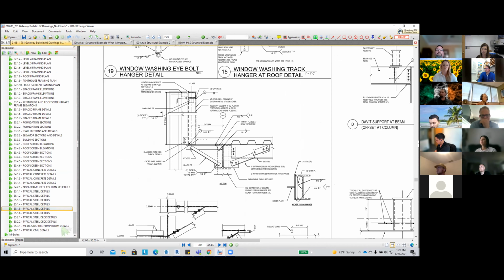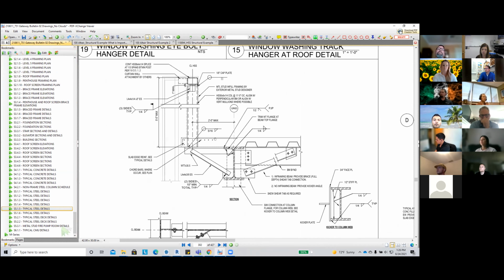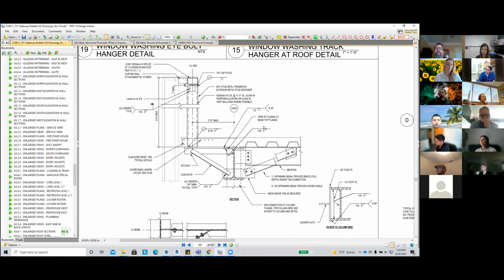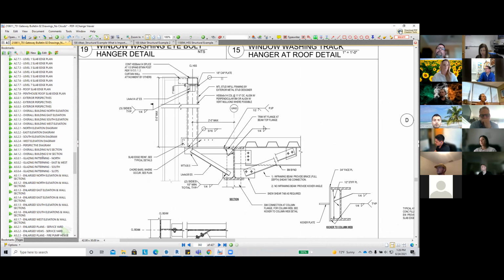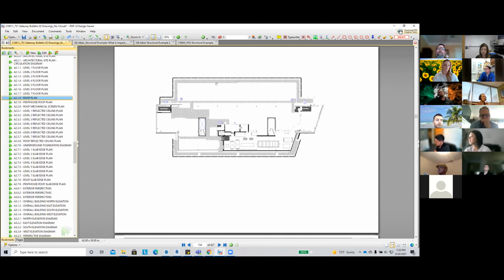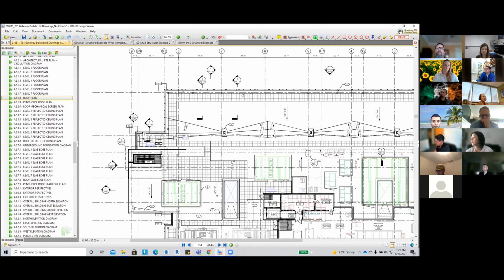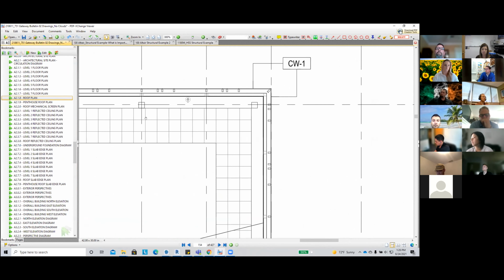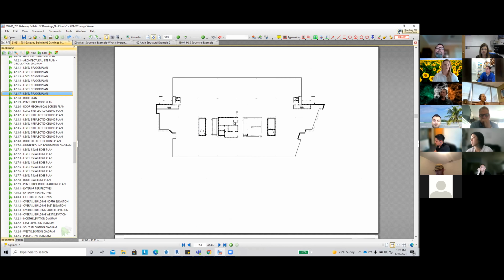Is that how you would check it, Paul? Well, I was going to say another way to do it is that same floor plan section, you should go to the architectural drawings, because the architectural drawings will give you from column line to face of system, which typically is to glass. And then if you use that dimension, you could work back to this one. So let's say it's 3'6". If there's a dimension from grid line to face of system, you can work your way back.